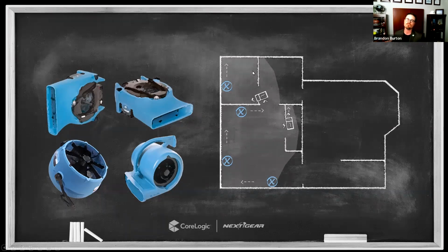You're basically using the wall assemblies. Here's a good way to kind of think of this. You're using the wall assemblies like a duct system, right? Where I'm moving the air along the walls as though they are a transportation system to move and circulate that air through the entire footprint of my drying chamber, right? That'd be another really good way to think of how strategically we're trying to place these.